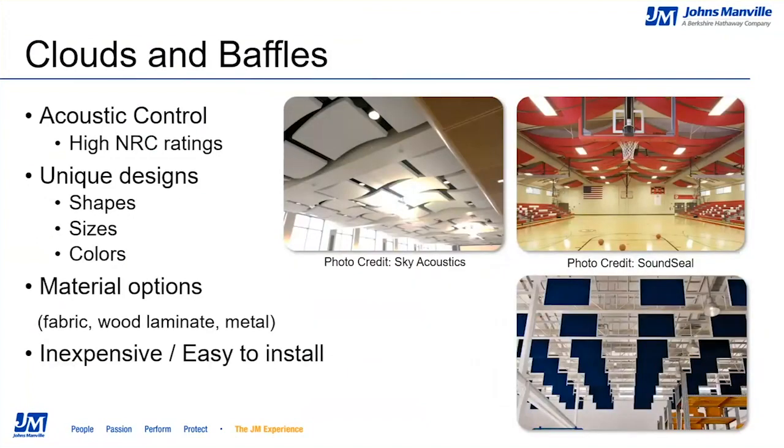If the office design doesn't include ceiling tiles, baffles and clouds are another excellent choice to control noise. These products have similar benefits to acoustical wall panels, but can be utilized throughout an office space. The unique designs, shapes, sizes, and colors available offer an infinite amount of creative choices. Many of the cloud and baffle designs include factory-installed attachment hangers, which make them easy to install with adjustable hanger wires. The spacing of the baffles should be considered if the optimal acoustical control is desired.